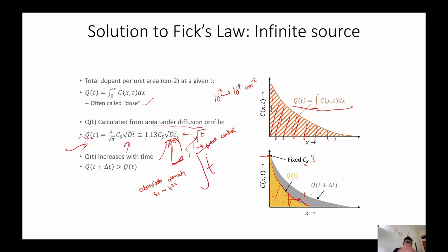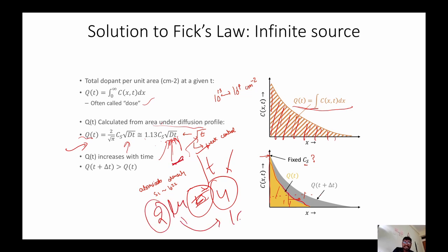If you have a silicon wafer and you want to diffuse boron, let us say for 1 micron of diffusion it takes 4 hours, but for 2 micrometers of diffusion it will take 16 hours.